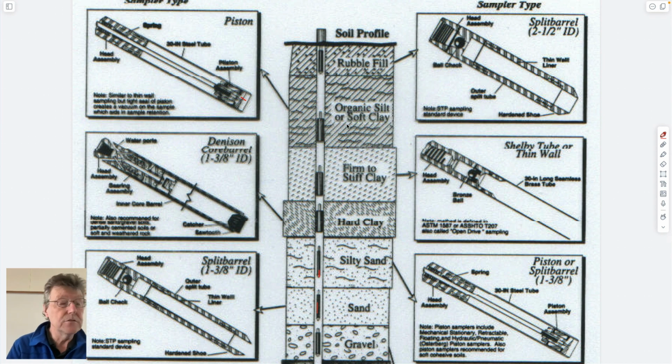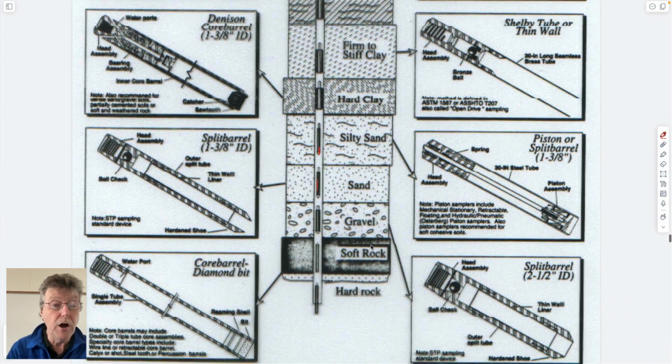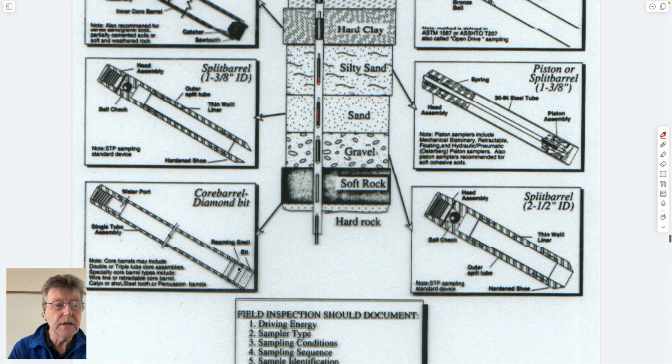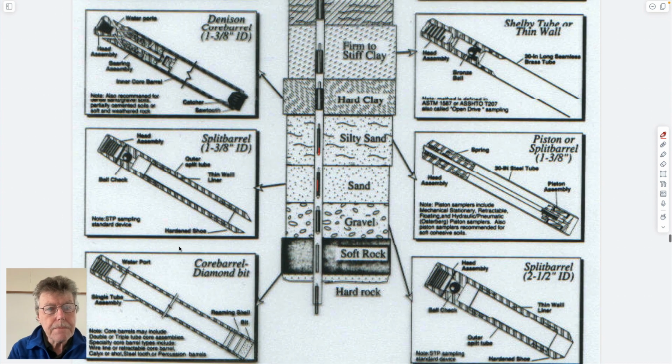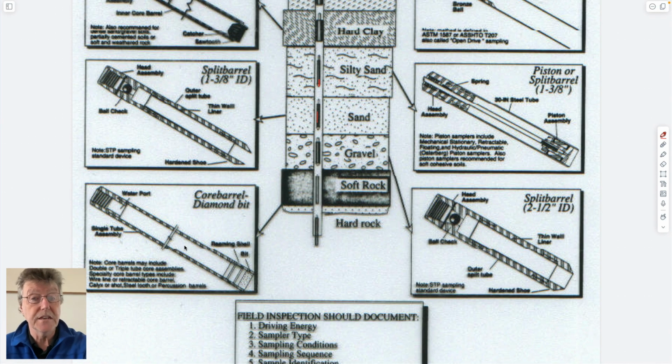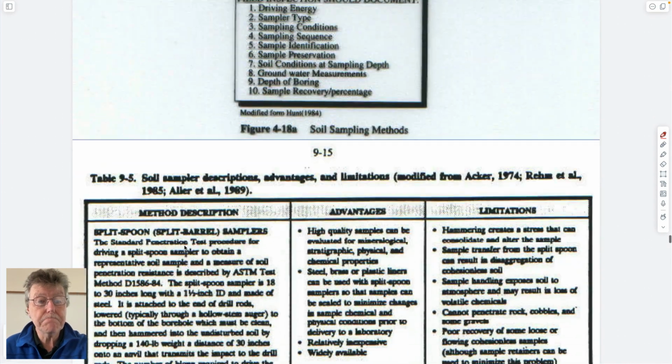And so those are the basic two types of core barrels. These are just variants of them. So either thin wall for clays, maybe silts, and thick walls for sands and gravels. And in rocks, we talked about core barrels. Core barrels have a diamond tip at the bottom, rotate, and the core goes up into it. And I guess we don't have more of those, so we'll look at some of those later in a moment.